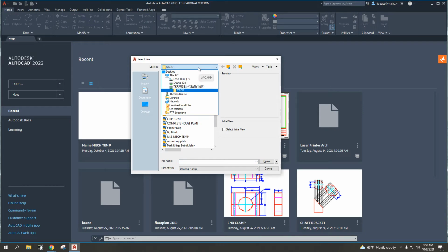The template file is kind of like that blank piece of paper that has a title block on it that we started with the board drawings. If you forget to utilize this file, there will be a number of things missing. Most importantly, the proper title blocks, as well as a whole bunch of internal settings in the files, and the line types / layers. And we'll be talking about that here.